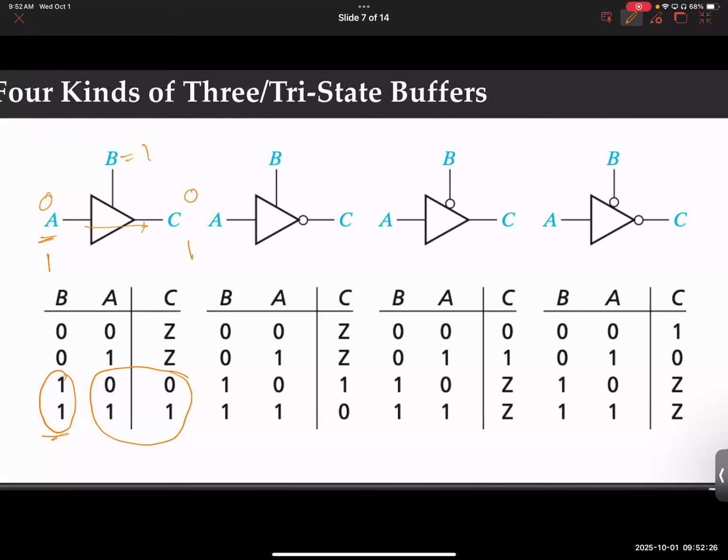If it keeps going up, that means the information that was stored was Boolean 1. If it gradually goes down by itself, that means the information that was stored was Boolean 0. That's how you sense it, exactly how we read blood pressure. You pump it and then you wait. Similarly, we pump the circuit with voltage or charge, and then we just let it float.